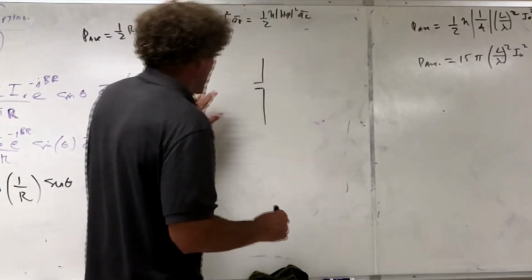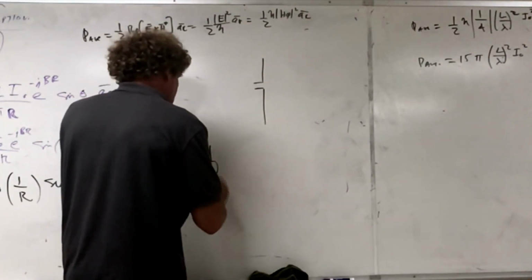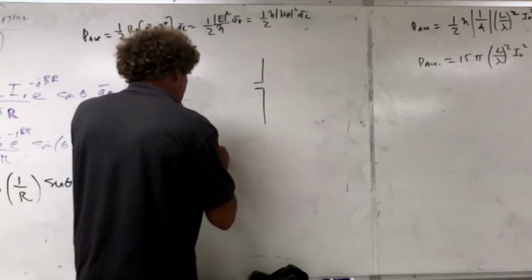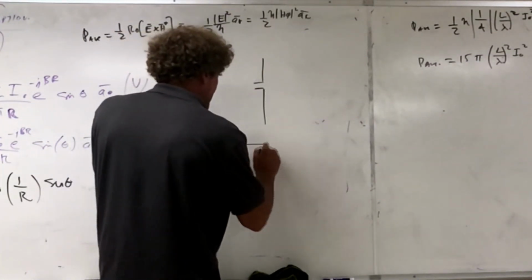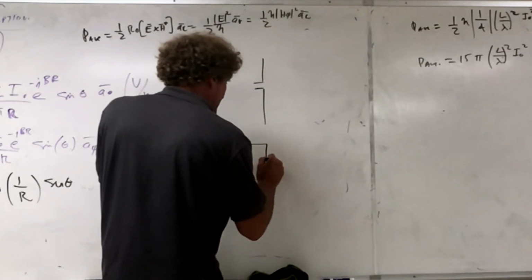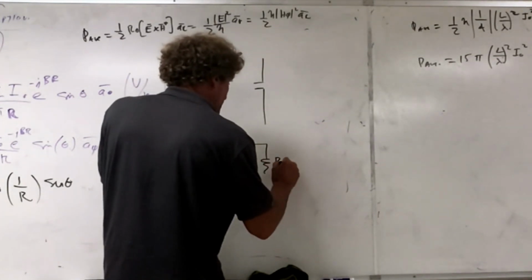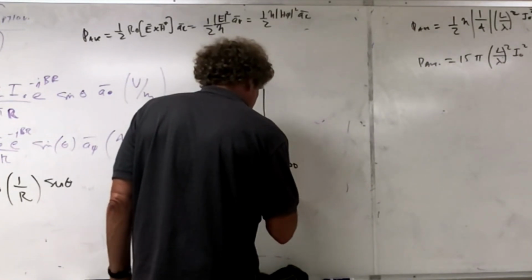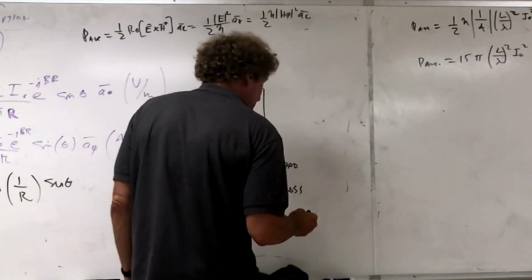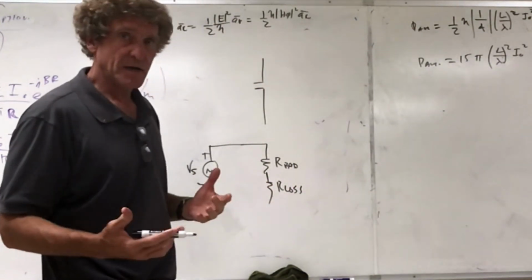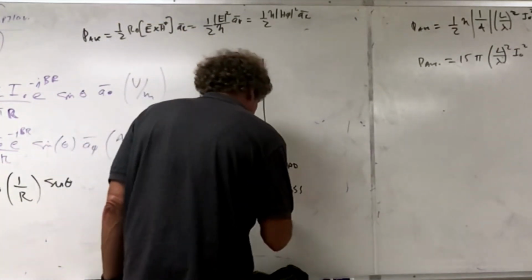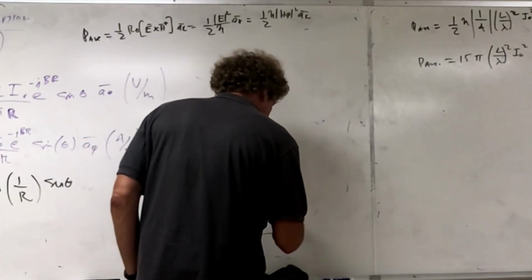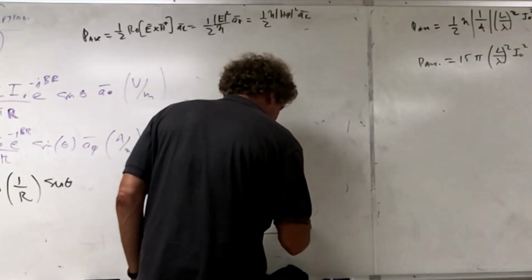So for this thing, then we'll have a radiation resistance. If I have a voltage here, some Vs, and I'm driving it, and I have my antenna here, the antenna can be modeled as some R radiation. Then there can be R losses that are a loss effect. That's really the copper losses, and I'm going to tell you what that is. And there's also a reactive value that we don't cover much. It can be X antenna here.